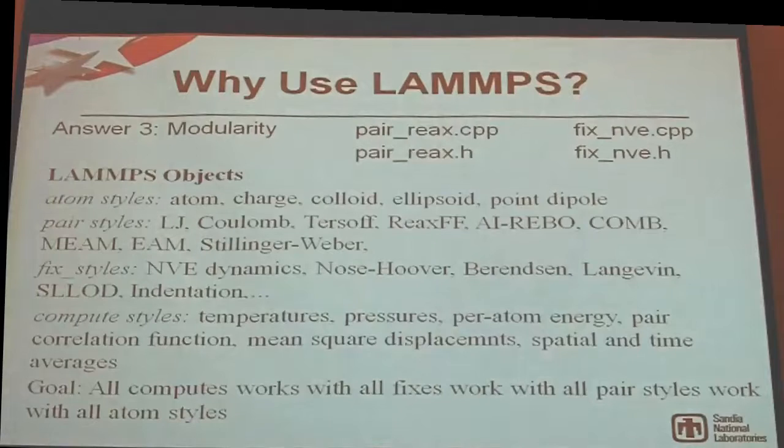Another answer to why use LAMMPS is its modularity. So it is built in such a way from a software engineering perspective that the pieces are modular. And you should be able to use any, what we call a compute, which kind of evaluates a quantity of interest that the user may have. Any compute should work with any fix, which determines kind of the thermostating and the time stepping and that kind of thing. And it should work with any pair style, which is really the force fields.